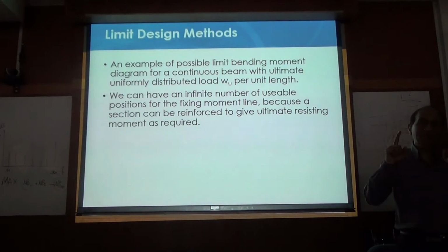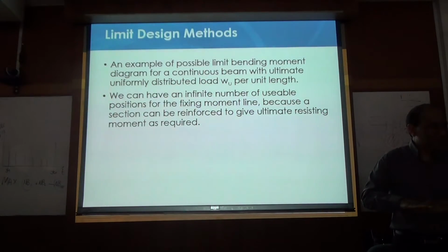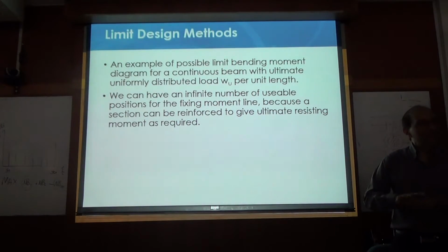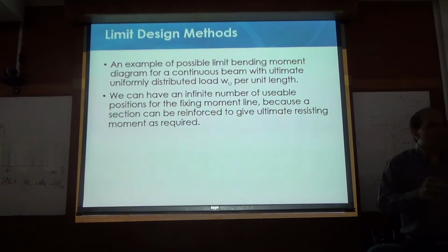That's why we allow cracking on the top of the beam, which is normally hidden by the flooring, so no one can see. And then we normally allow cracking to happen for dead load before finishes. That means after finishing, there should be no cracking. So those kinds of things can help to control this phenomenon.